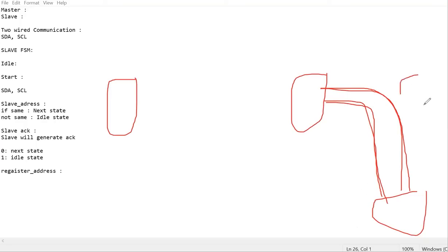Okay, here we will connect some other protocols like the APB protocol, a bus protocol. So the slave will convert that parallel data, and through the APB bus protocol we will send it again to another master, that means another IP or another block. Okay, so in between this is the I2C protocol, which is a serial communication.